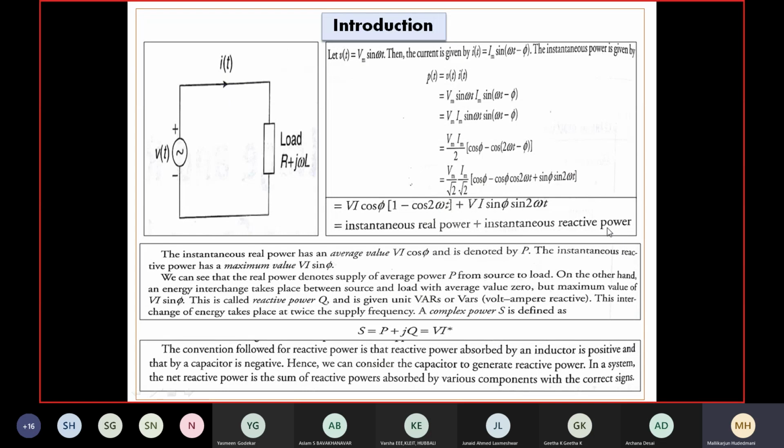We all very clearly know this reactive power is very important. It is an oscillatory power, to and fro, moving from source to load, load to source continuously. But the active power is being consumed by the gadgets or equipment to perform their intended application. So these two powers are very important for us because there are a lot of consequences connected to them.